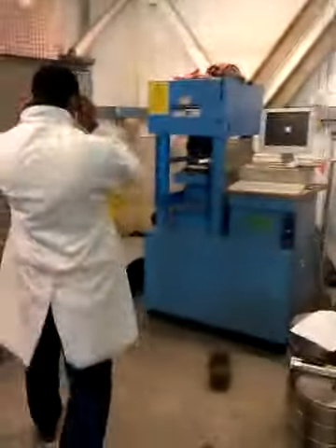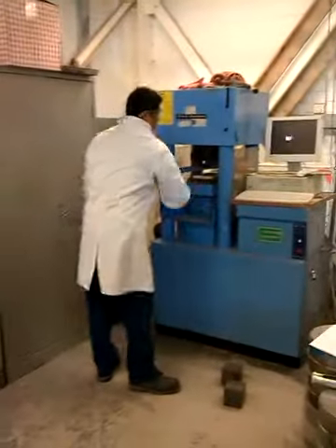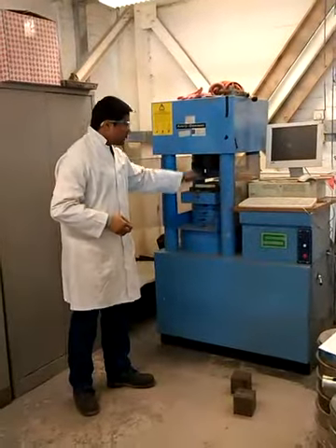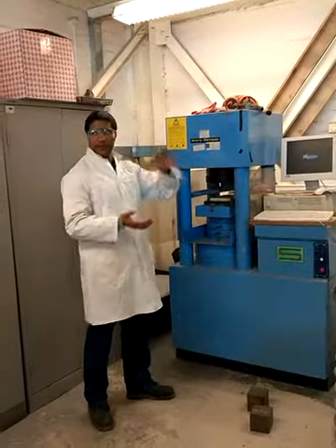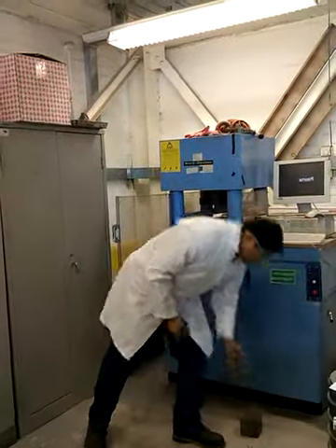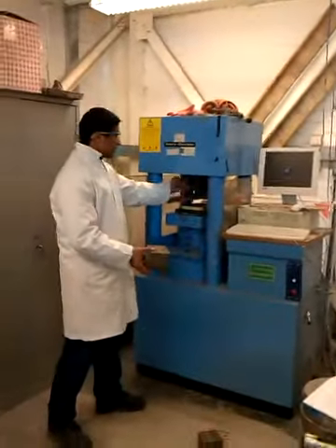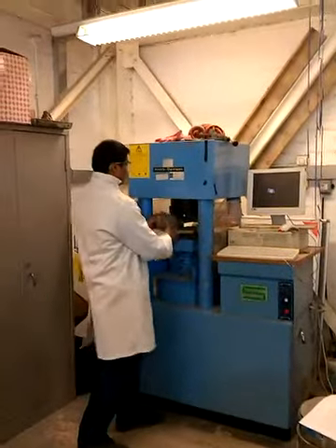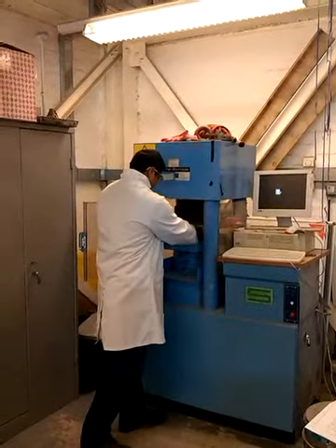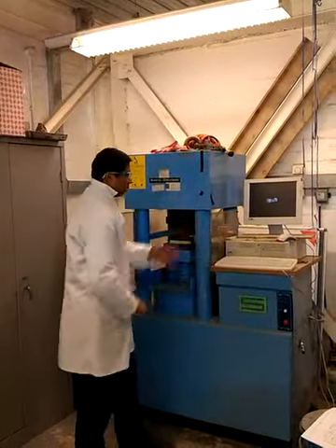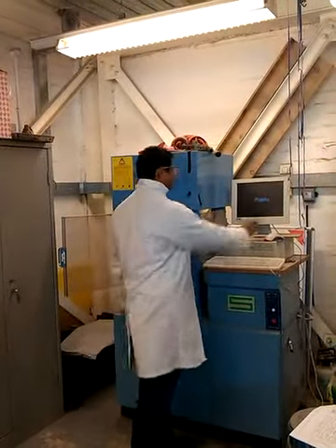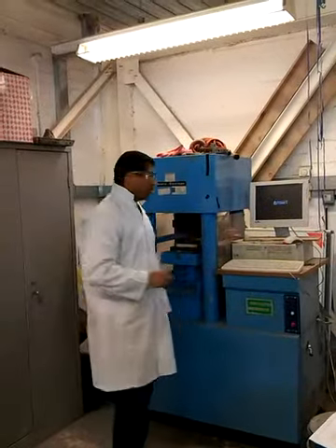This is the compressive strength testing machine, where you can see the ram. Once you apply the load, the ram will come up and crush the cubes. When you put the concrete cubes, you select a smooth surface on the top and the bottom side of the ram and keep it at the center of the ram. Then we will select the rate of loading, that is 6 kilonewtons per second. Okay?